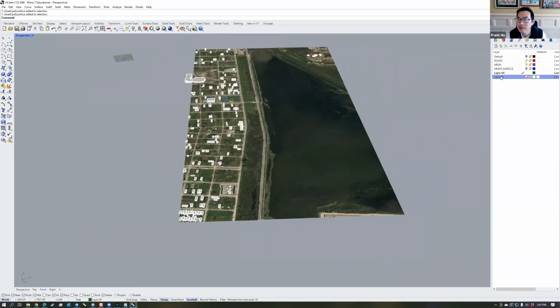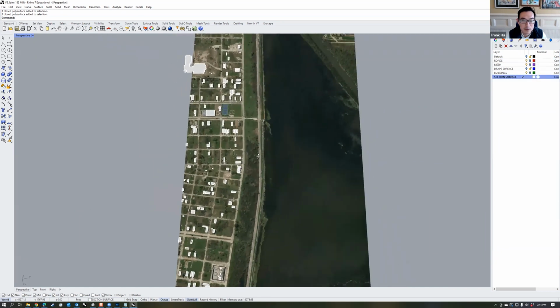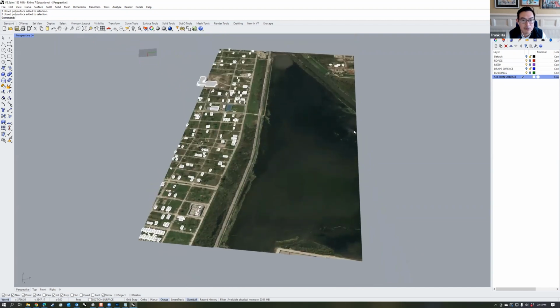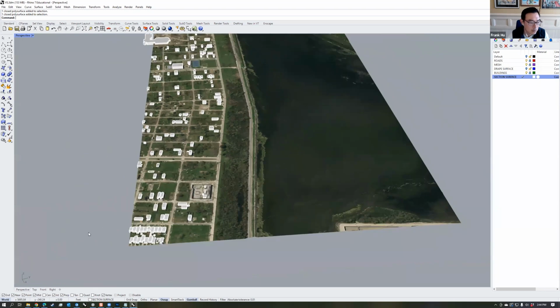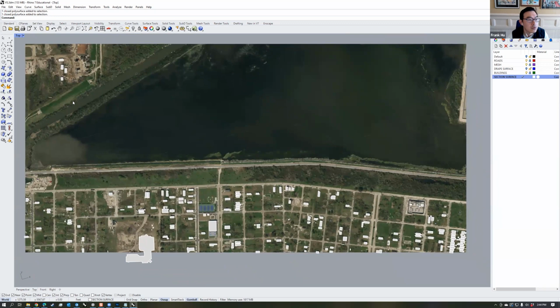Let me create something called a section surface first. I'm going to create a layer called section surface. And in section surface, we're going to draw a vertical plane that represents where you want that section cut to be. So a section like that is probably what we want. I'm going to go to a top view first and create a vertical surface. In the tab on the side, I'm going to choose the surface button and then this vertical plane tool. Now you pick an area.